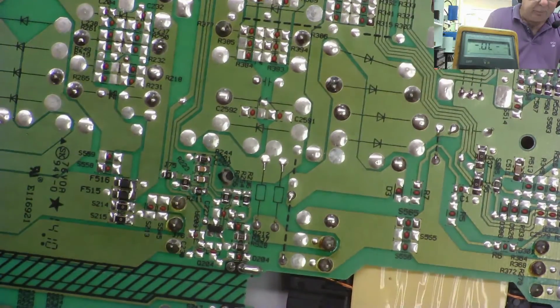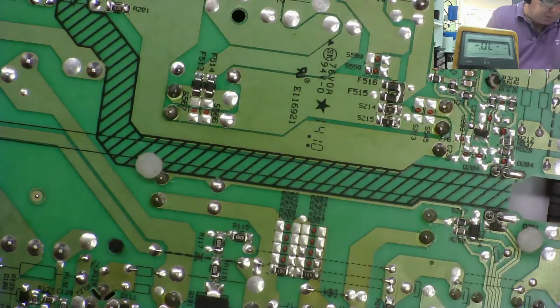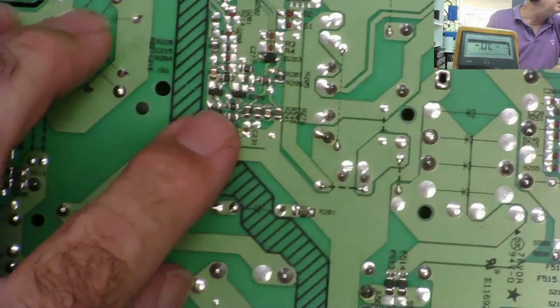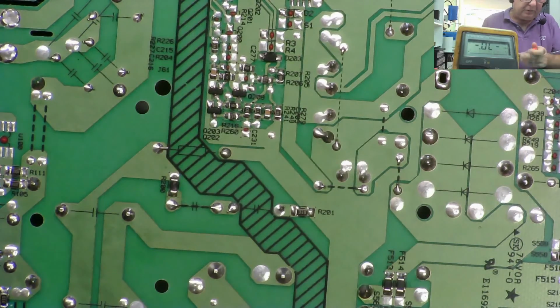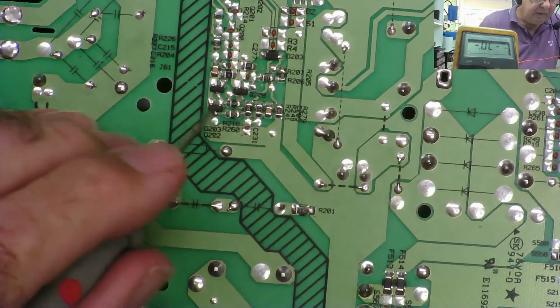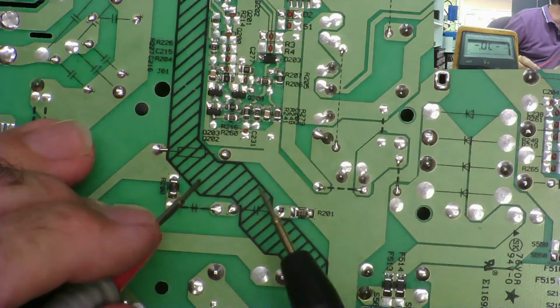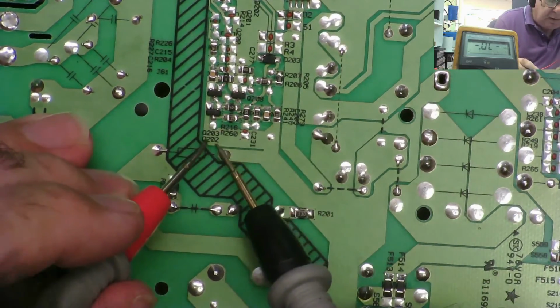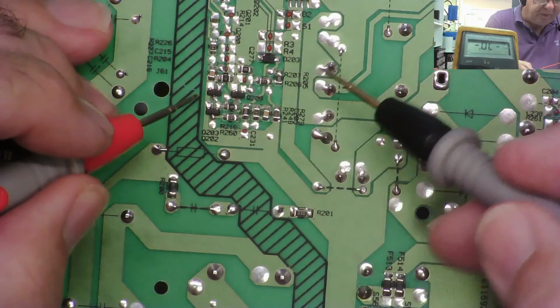Last thing, let's have a look around on the resistances, and let's find some surface mount. There's some surface mount transistors on here somewhere. Yeah, there's a little group of them here. These little packages called small outline transistor 2-3, which is 2mm by 3mm, I think. SOT 23, yeah, 3-pin. These are often transistors. They're marked here as Q202, Q203, Q208. They probably are transistors, but they could be FETs.